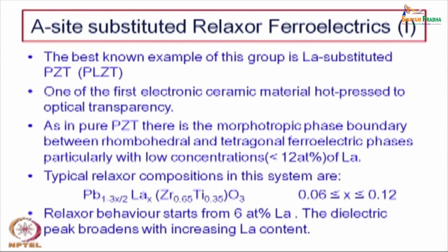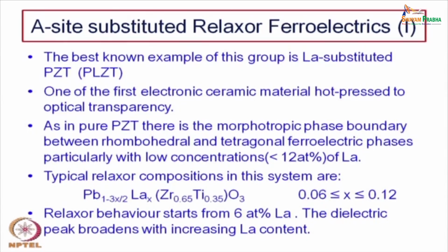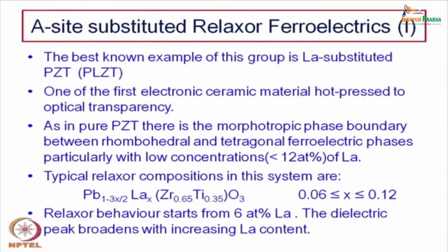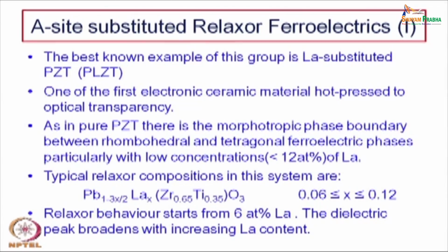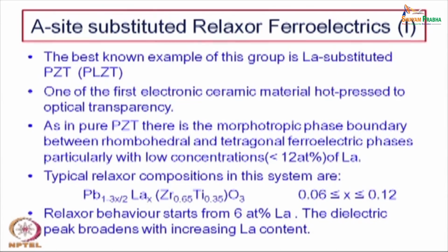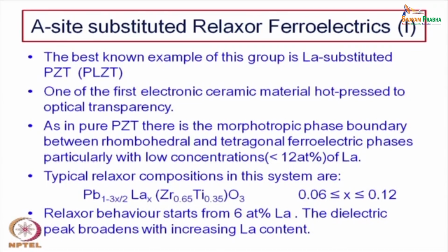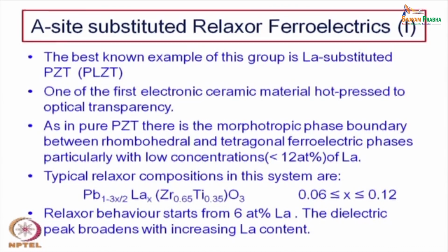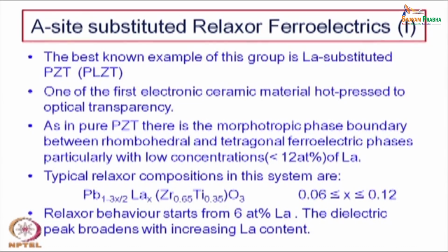Well, that was all about the B site substitution. The other group, as we mentioned earlier, is the A site substituted relaxor ferroelectrics, and once again this is based on the most popular piezoelectric material, that is PZT. In fact, PZT has been substituted, where some fraction of lead has been substituted with lanthanum, and of course this PLZT, lanthanum substituted PZT, has a very important characteristic, and it is one of the first electronic ceramic materials hot pressed to optical transparency. Okay.